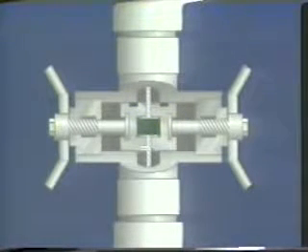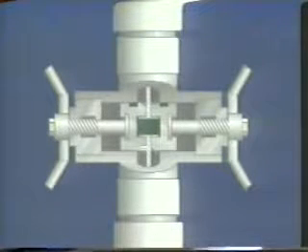The wireline valve is designed in such a way that when the valve is closed and pressure is released above the rams of the valve, the well pressure trapped below the rams holds them in a closed position. To reopen the valve, pressure must be equalized across the rams.